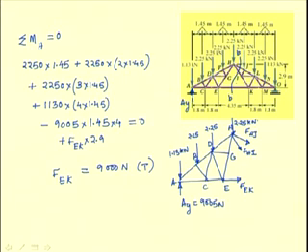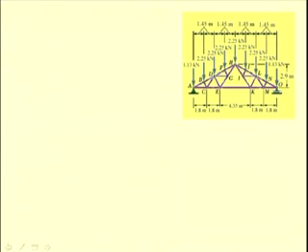So, from this free body diagram we have determined the force in the member EK. Now, it is possible to move to the free body diagram of the portion which is sectioned by the section surface AA, that is, it passes through the members DF, DG, EG and EK. So, let us draw the free body diagram of this section.